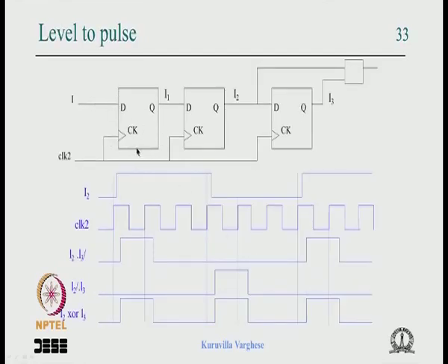Okay. Now this is a practical circuit. I am putting two synchronizing flip flops. We have not studied why the synchronizing flip flop is required. That is basically to meet the setup time here. Otherwise this flip flop can get into something called metastability.